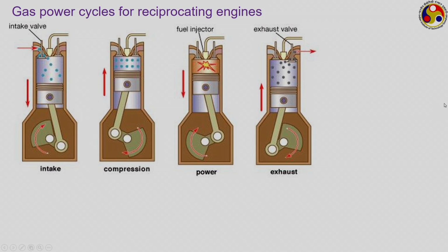Now, this is a brief summary of what we have seen. In reciprocating engines, we have seen that a 4-stroke cycle generally has 4 strokes comprising one cycle: the intake stroke, compression stroke, power stroke, and the exhaust stroke. And that is true for both SI engines and CI engines. Once we apply the air standard assumptions on them, we generally can identify 4 processes to resemble these 4 strokes. The first process is compression, which is a representative of this particular stroke.